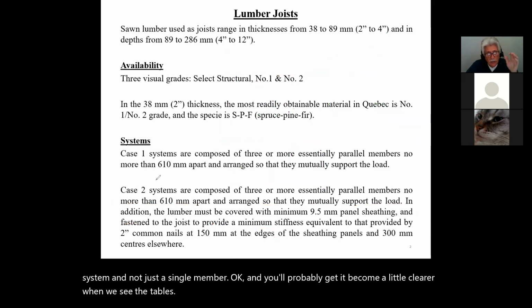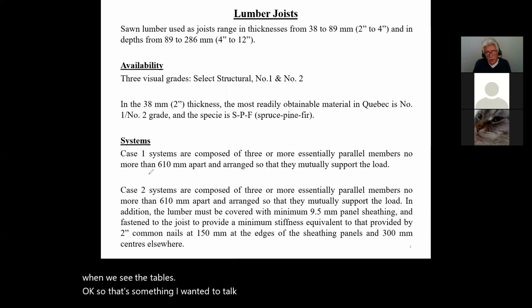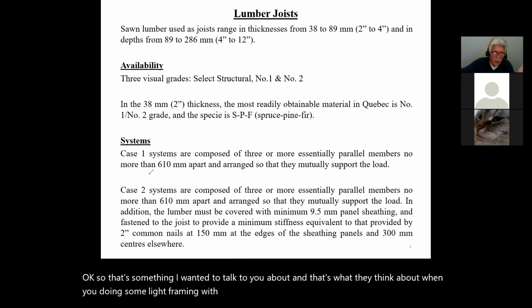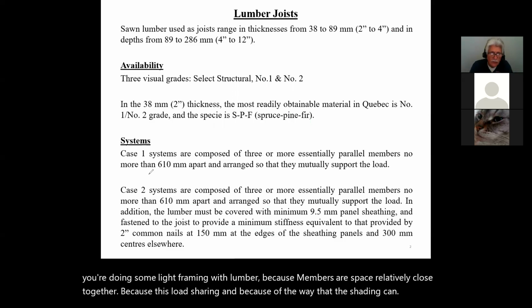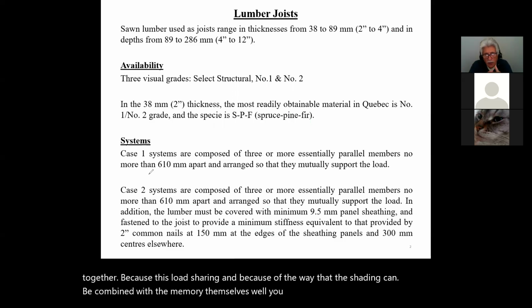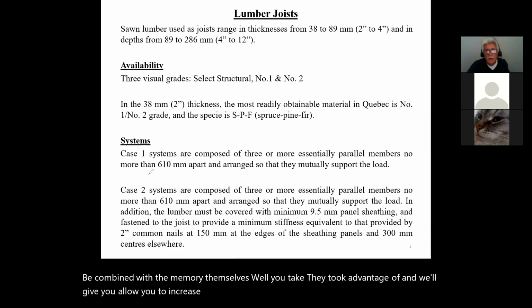Okay, so that's something I wanted to talk to you about. And that's the thing about when you're doing some light framing with lumber, because members are spaced relatively close together, because of this load sharing, and because of the way that the sheeting can be combined with the members themselves, well, they took advantage of that, and will allow you to increase the resistance of those members.